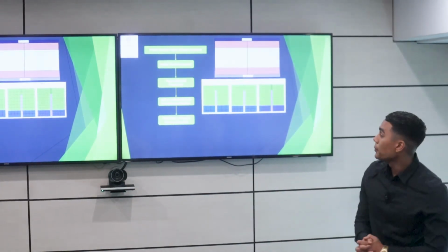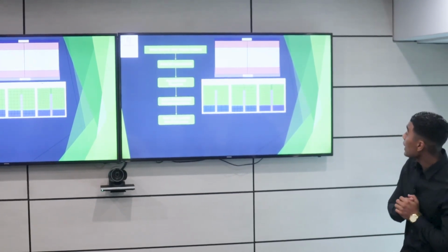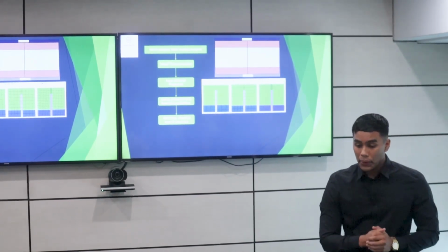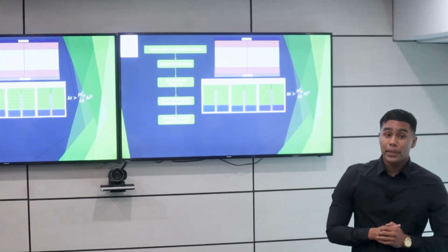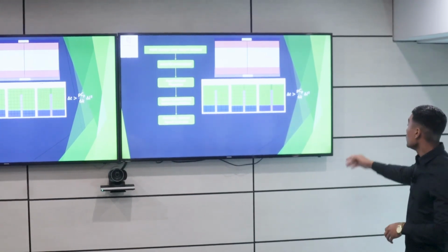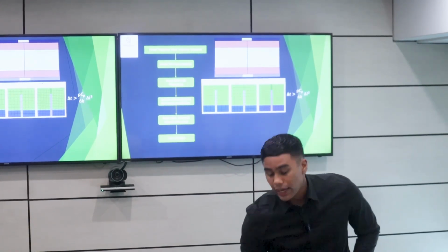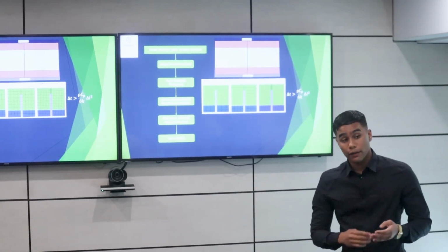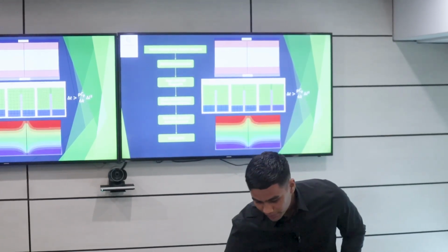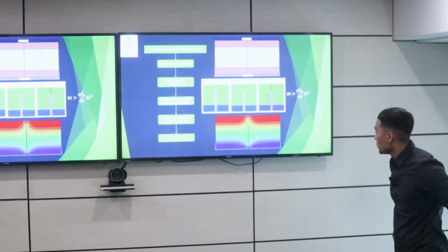Mesh size, element type, and time step. 4-node linear quadrilaterals were used. 3 mesh sizes were considered, and mesh 2 was chosen because temperature results converged at this size. 1 hour time increments in seconds was chosen, which is achieved by that equation, which is specified by Abaqus to avoid false oscillations. And finally, I ran my analysis. There were 4 wall tie materials and 4 insulations, which makes 16 analyses. This is a visualization of heat flow from the external to the internal face.